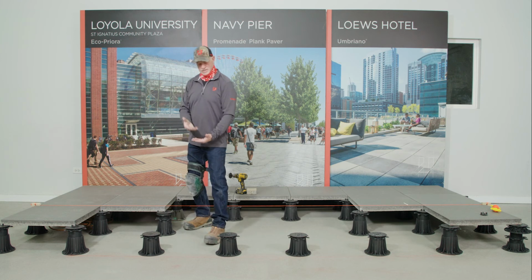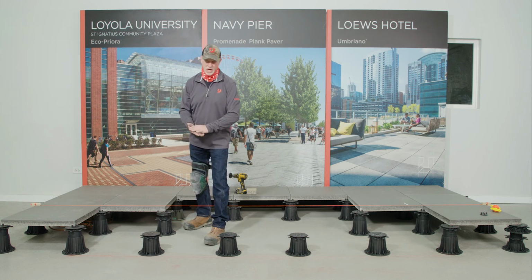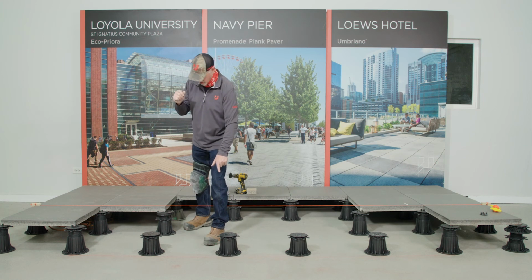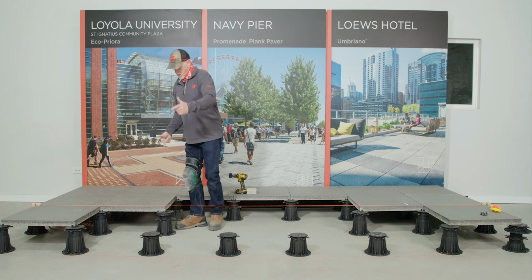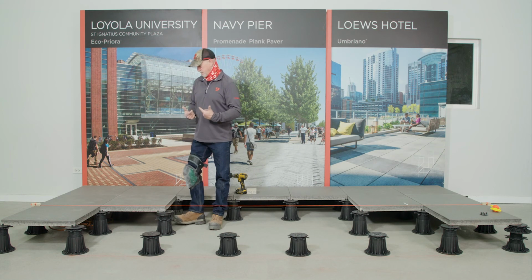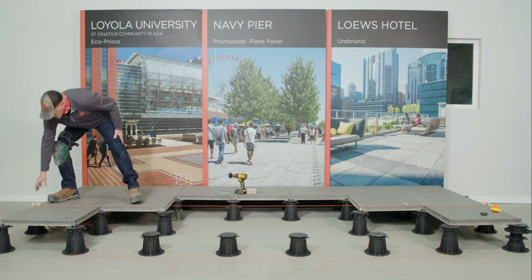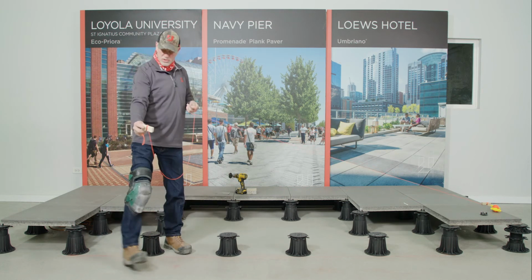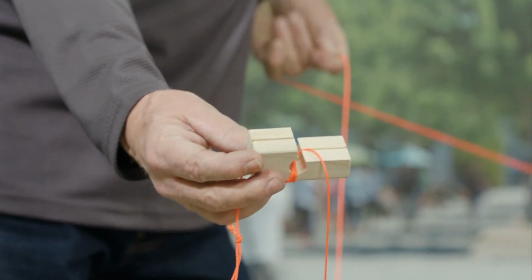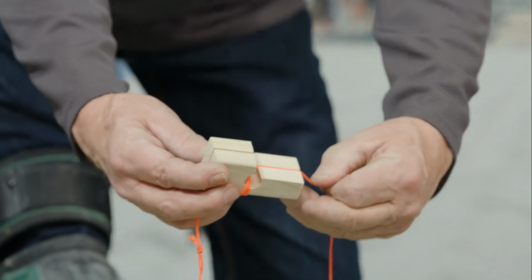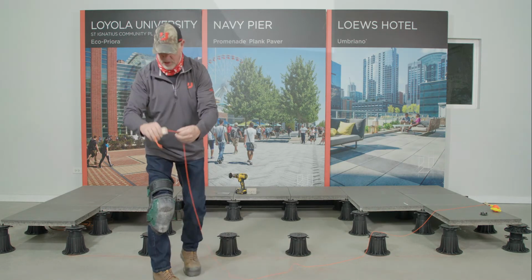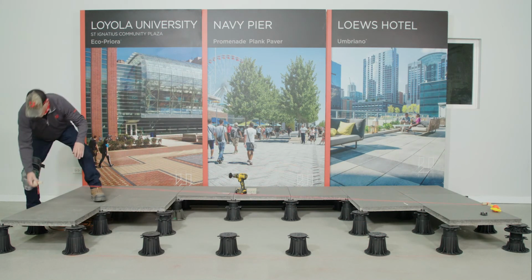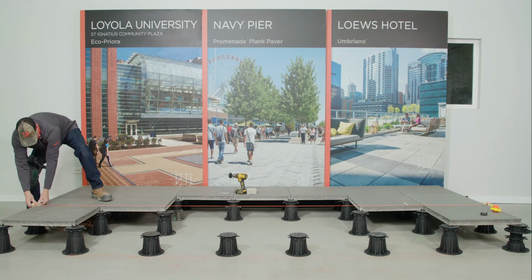It could be high density foam with the geotextile, which makes it hard to accurately mark a line, just as Brad and I have done. So oftentimes we'll use a dry line over the top side. One of the things that I like is the use of a line block, and I'll bring that up and show you. So in masonry, oftentimes you're going to see a line block. It's got grooves to accurately hold the line in place. And I'll set that at the top height elevation with significant tension to it.